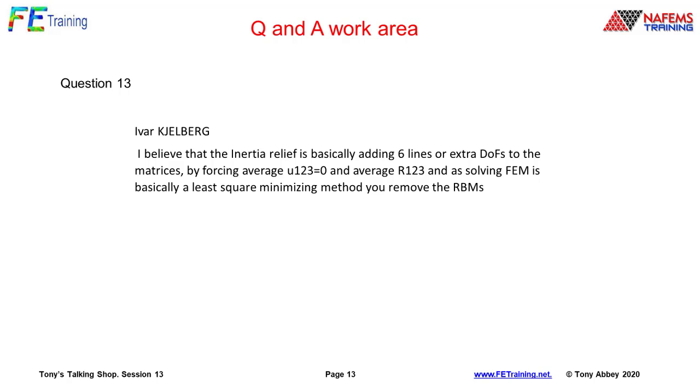The mathematics behind it, I did dive into it sort of 10, 12 years ago, and again it comes back to Steve's point. I've skipped the mathematics behind there. There are some implications in there, which is why I actually prefer to use user-defined support positions. Think about the 3-2-1 type approach, and have a kinematically feasible way of constraining out those rigid body modes.